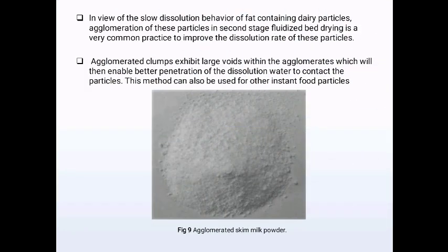In view of the slow dissolution behavior of fat-containing dairy particles, agglomeration of these particles in second stage fluidized bed drying is a very common practice to improve the dissolution rate of these particles. Agglomerated clumps exhibit large voids within the agglomerates, which will then enable better penetration of the dissolution water to contact the particles. This method can also be used for other instant food particles. Figure 9 shows the agglomerated skim milk powder.